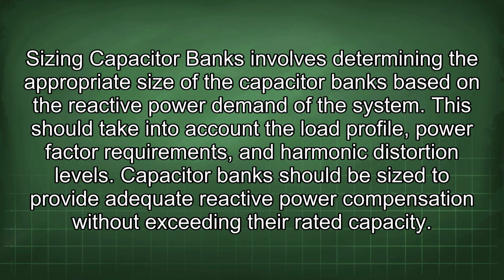Sizing capacitor banks involves determining the appropriate size of the capacitor banks based on the reactive power demand of the system. This should take into account the load profile, power factor requirements, and harmonic distortion levels. Capacitor banks should be sized to provide adequate reactive power compensation without exceeding their rated capacity.